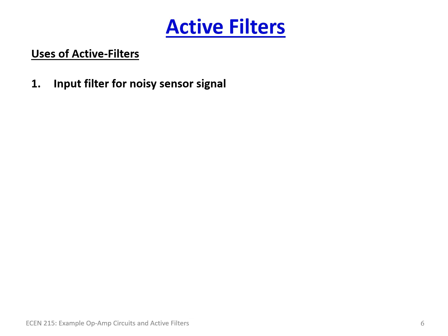And so all of these kinds of noise sources can sometimes end up getting superimposed upon a sensor signal, like a strain gauge or temperature or pressure, and so on and so forth, of a mechanical system that you're actually trying to measure. As such, you want to filter out some of these higher frequency noises, especially if your signal needs to be low frequency.